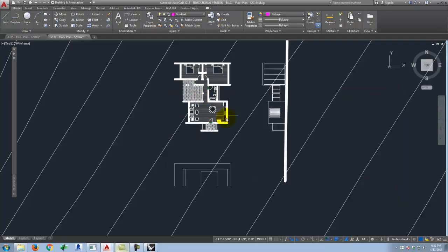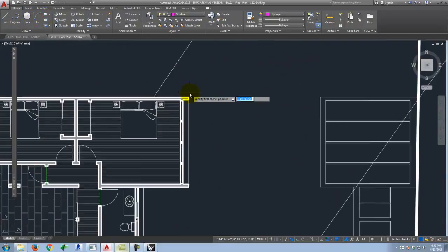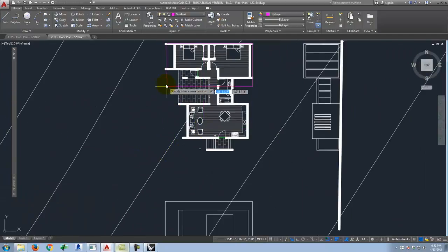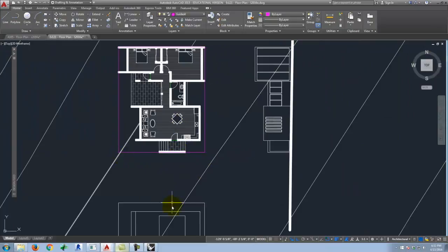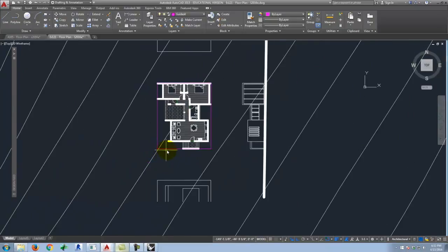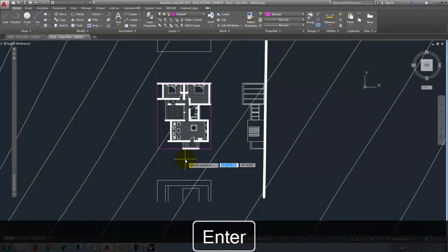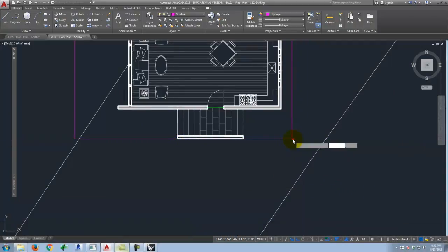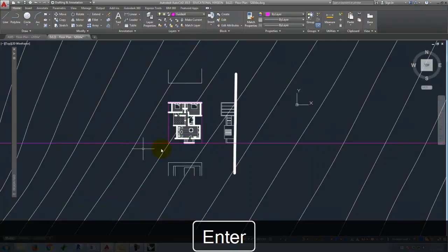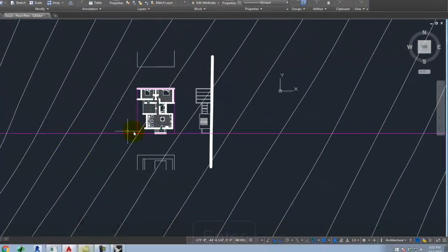So now I need that bounding box. So I'll draw it again from this corner to there and to right there. Perfect. There's my bounding box. So this elevation is coplanar with this edge. So I'll do an X-line, construction line, that goes in that direction. And I will once again mark the points at which it crosses the topo.